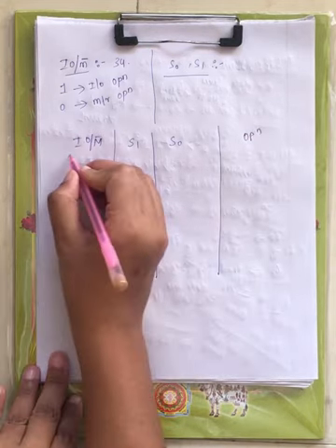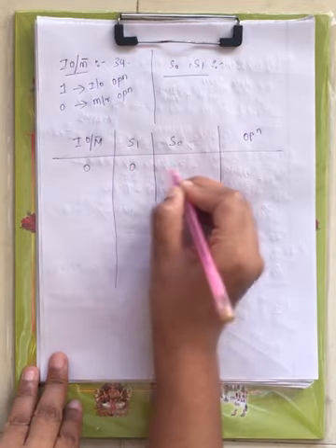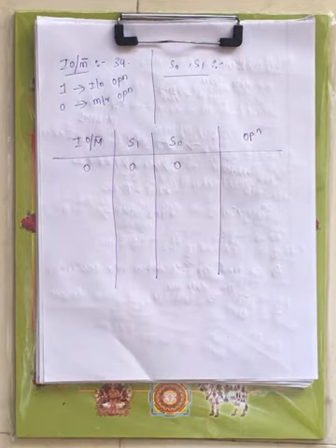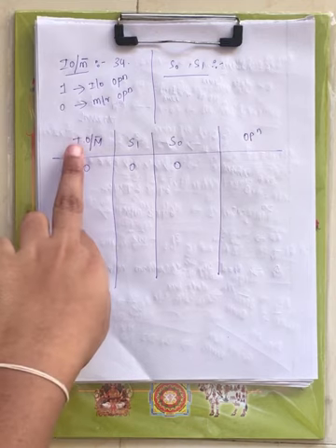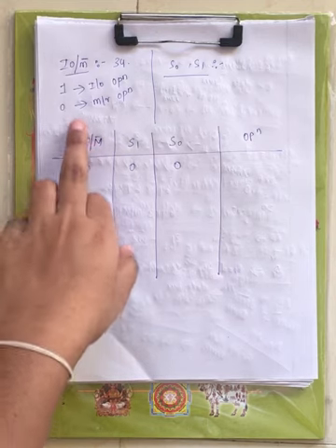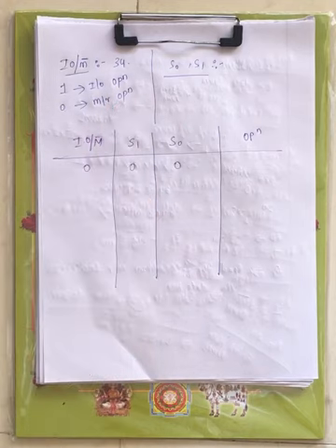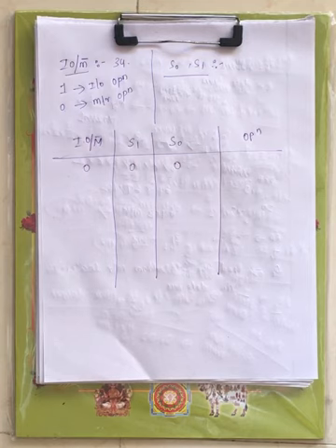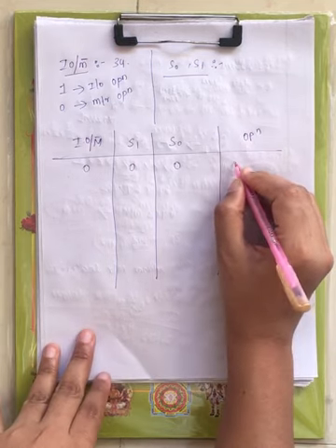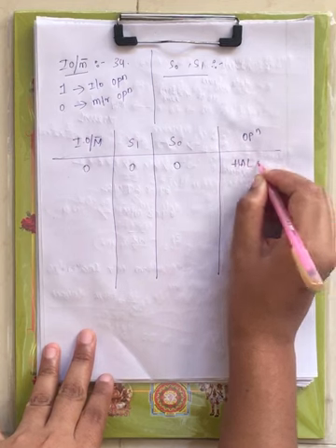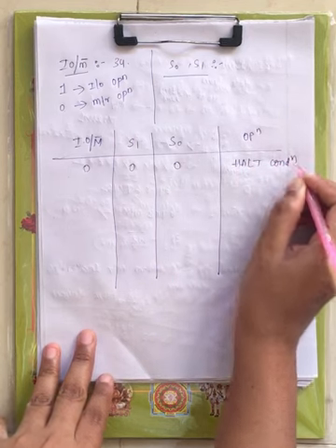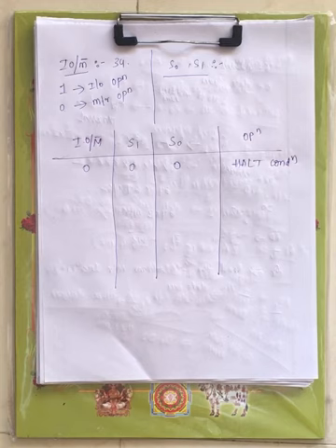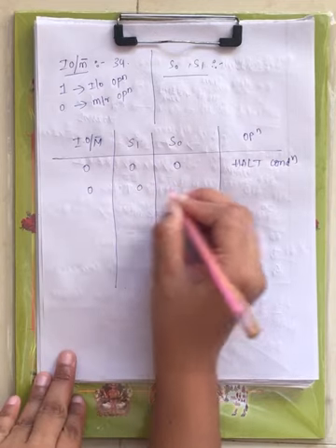Now when all are 0, here IO/memory bar is 0, which is a memory operation, and when the status signals are 0, the microprocessor is under halt condition, because when the two status signals are 0, the processor is not doing any operation.